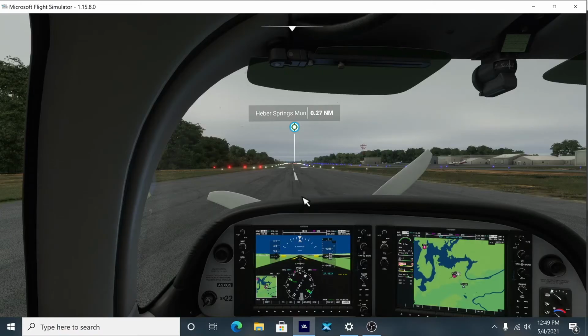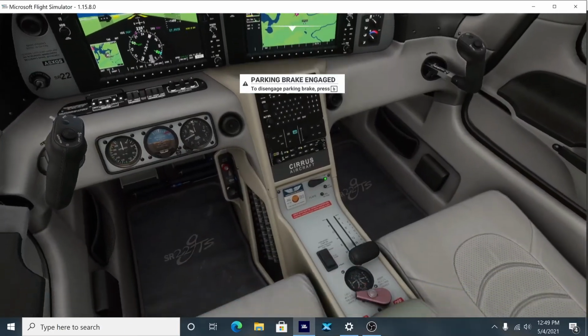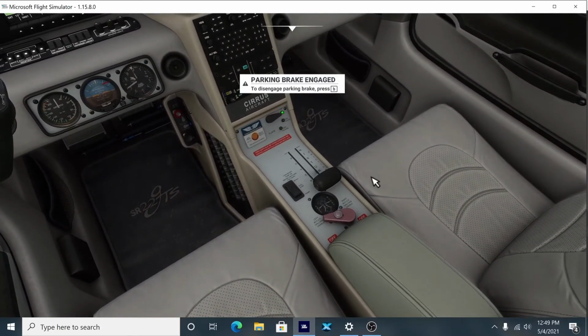Alright, so now that we're in the cockpit, we can look down at the throttle quadrant to make sure that everything's working the way it's supposed to. So our throttle, full throttle, and idle. Mixture goes all the way rich and all the way lean. Our fuel selector, if you go to right, left, or off. Now there's not a command for the left sided off and the right sided off, so it all goes down there to the right sided off. The flaps should just move one at a time. And then when you move them all the way to the top, they should go up.